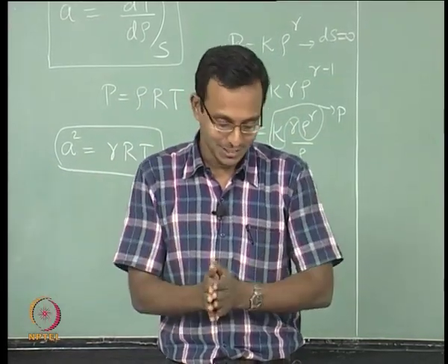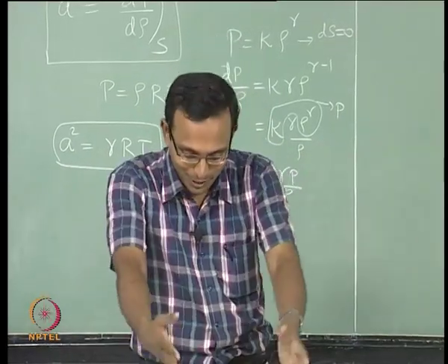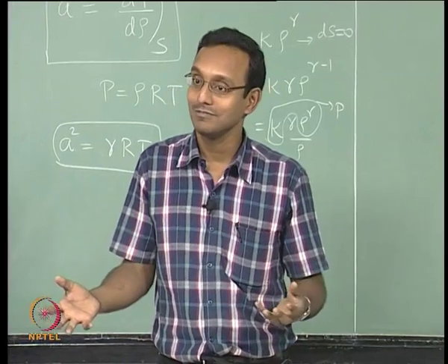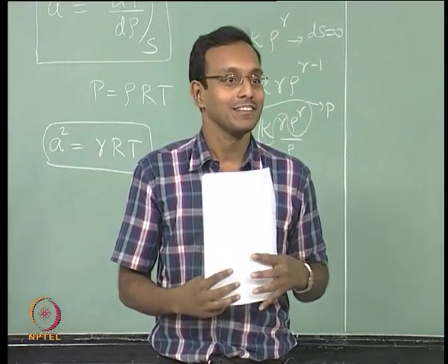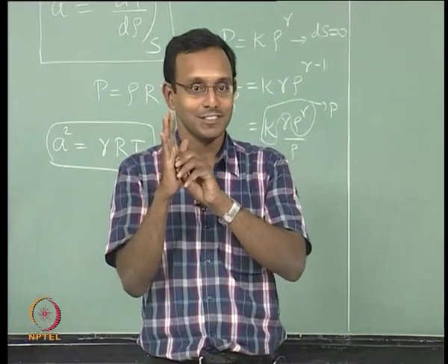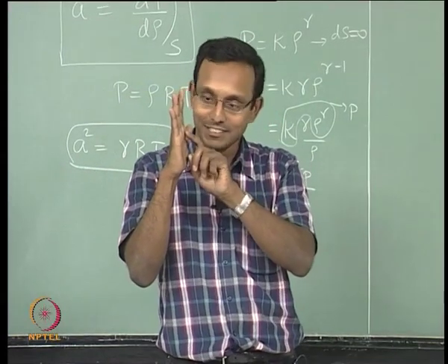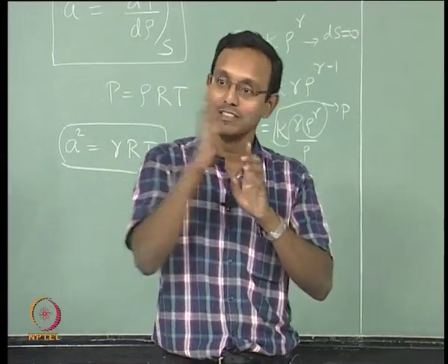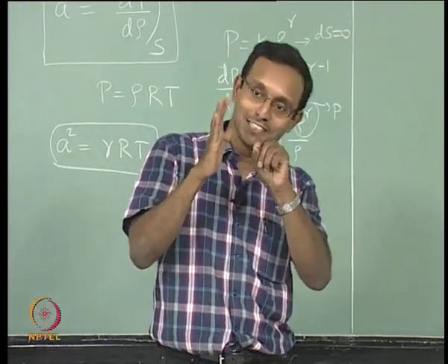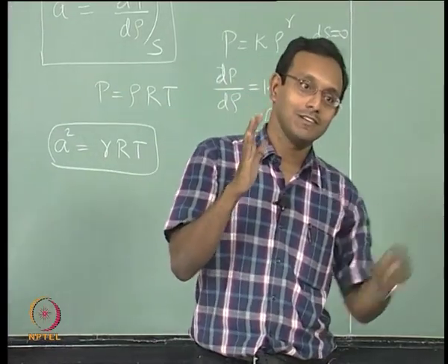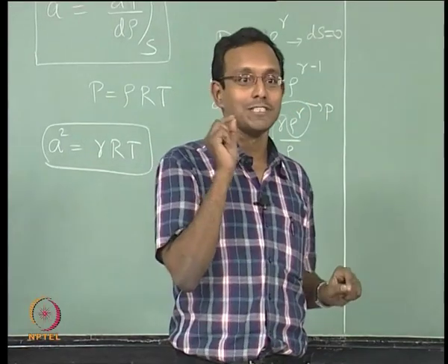I am going to think about it as, say I am going to move my hand towards this paper, there was a puff of wind going towards this paper somehow. How? So I will hold it like this and I go, there is a puff of wind going that way. Why? That pressure pulses, this fluid element very close to my hand tells the next fluid element that this hand is moving this way. Okay? Because of that, that next fluid element is telling the previous one, that is telling the next one, that is telling the next one, but it does not tell instantaneously all the places, it tells at a specific rate.